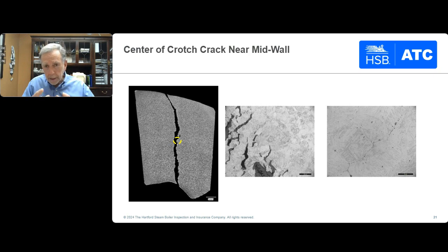But the primary one is that, as Jay indicated, although ASME doesn't identify a design life for any of their systems, when you look at the way the allowable stress values are calculated for these materials and look at the factoring involved on the various test data that has to be supplied in order to calculate the allowable stress values, if you follow through on the mathematics, even if you have the worst possible material properties, you should have a minimum life somewhere in the range of 250 to 300,000 hours. And yet, as Jay showed earlier, these failures are occurring in fractions of that particular time.